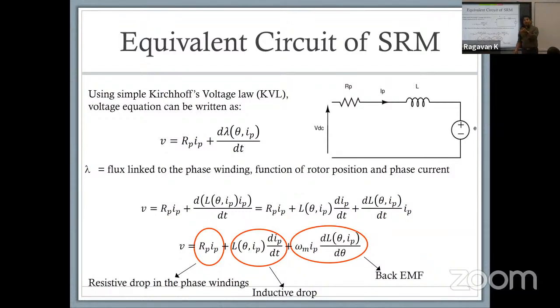It dissipates its stored energy, right? Whatever the magnetic field has stored, that energy is dissipated. So that will then lead to current that does not go straight down. If you had a purely resistive circuit, your current would have been a straight drop, right? Because of the presence of the inductor, it will gradually discharge and create a tail. It basically gives you a slope which has a time constant, the RL circuit, right?